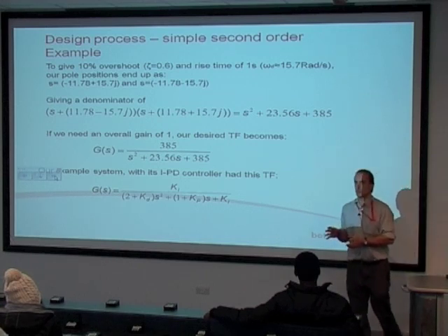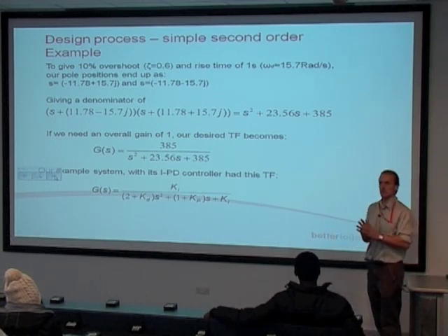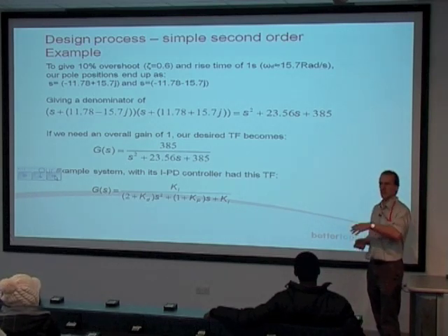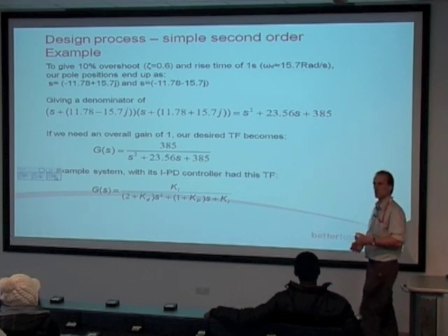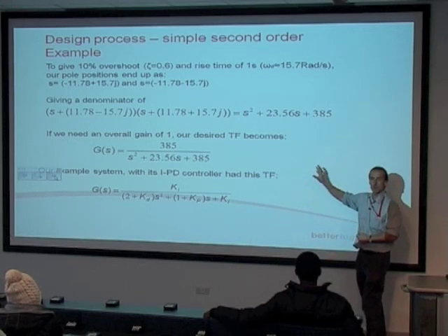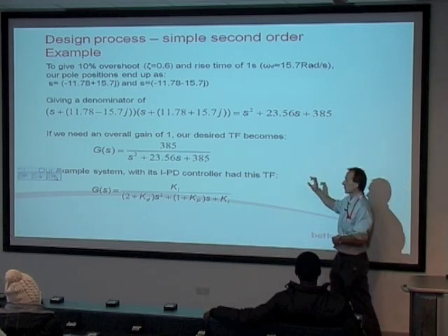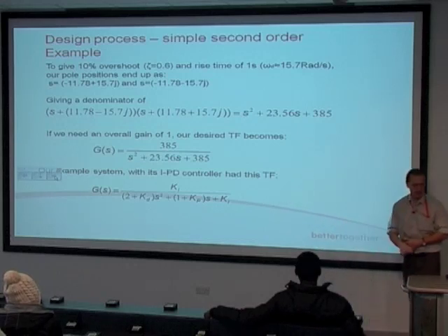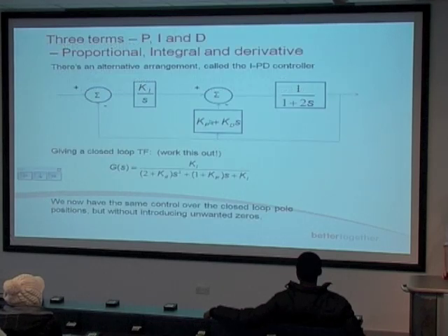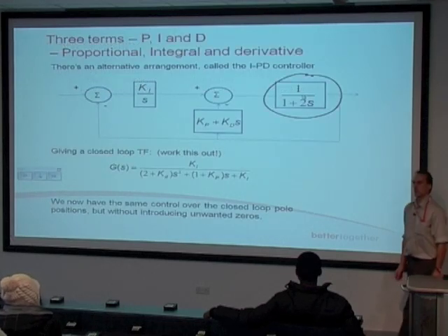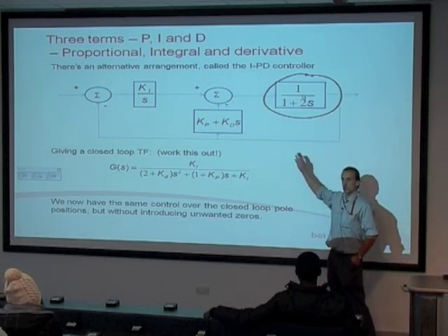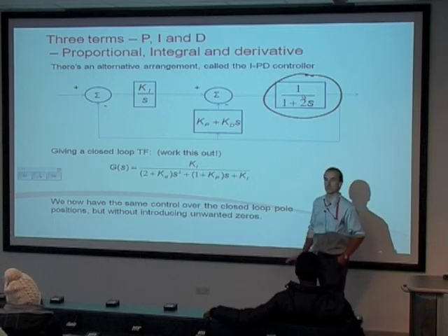The empirical methods that I mentioned to you have got one significant difference to this. Okay, so I know I slightly rubbished them earlier on by glossing over, but the key thing about these algebraic methods, these methods only work correctly if we've got an accurate model of the system in the first place. We need to know the model transfer function for these algebraic methods to work. If we do, everything's dandy, no problem at all.